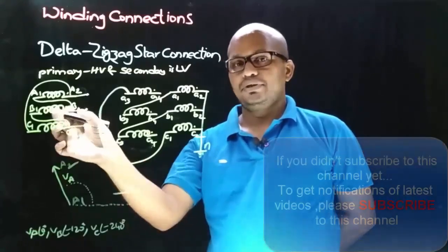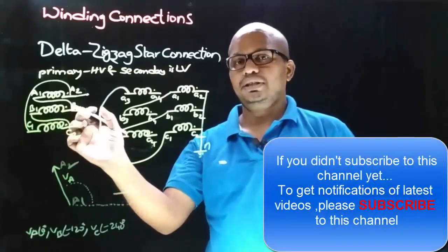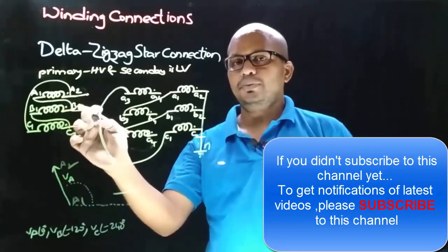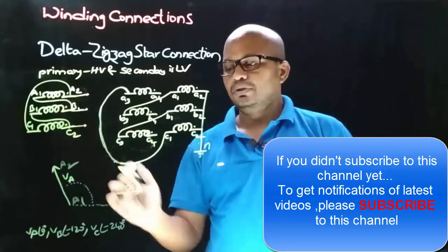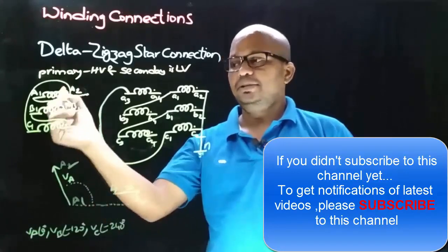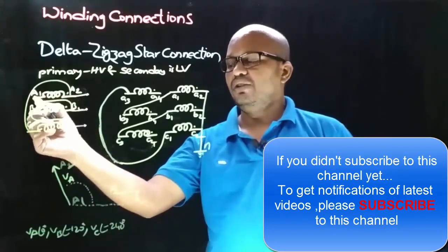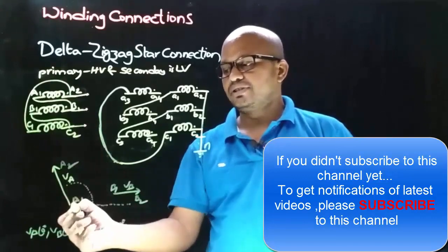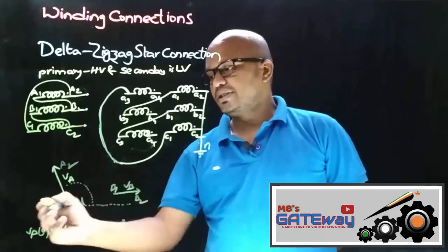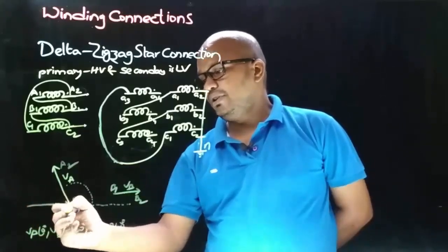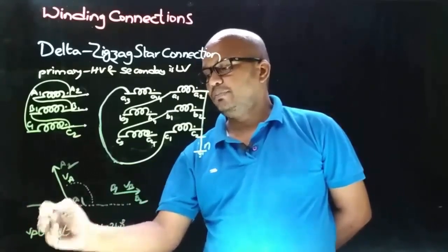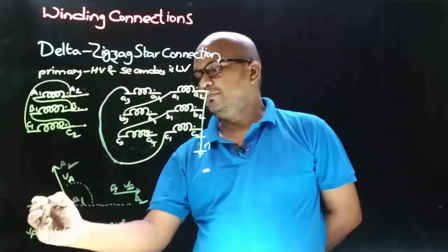this VB phasor, and observing winding connection that B1 and B2 are the terminals of this B phase, and as the connection is took from dot end terminal, that is B2, therefore arrow will point towards B2 and other end will be B1. And in primary side winding connection, A1 is connected to B2, means in the phasor diagram to A1 there must be B2 end. Therefore place this phasor such that A1 will have B2 end. So this is the VB phasor, so other end will be B1.